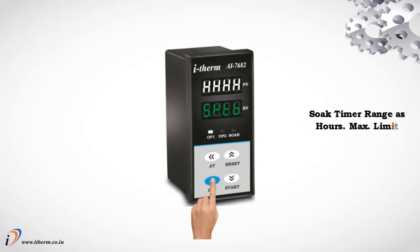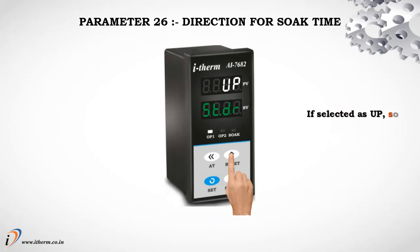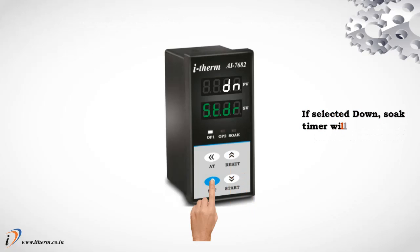Soak timer range as hours. Maximum limit 9999 hours. Parameter 26, direction for soak time. If selected as up, soak timer will increment from 0 to set value. If selected down, soak timer will decrement from set value to 0.